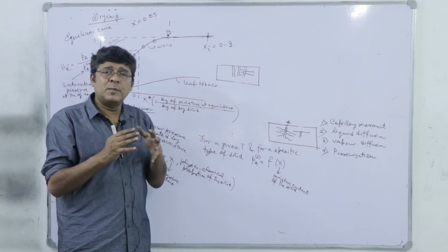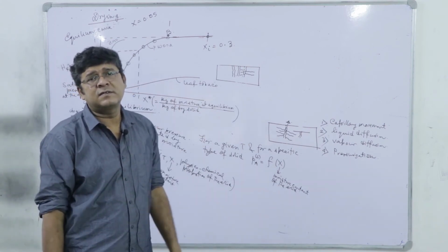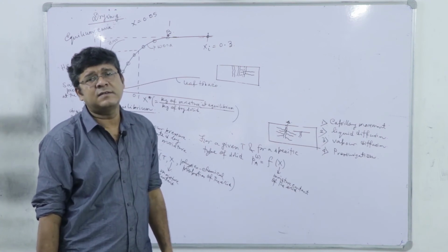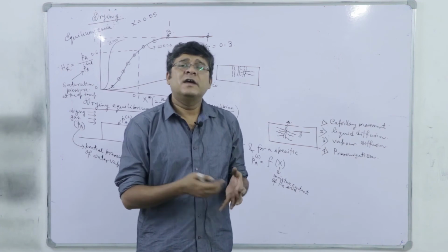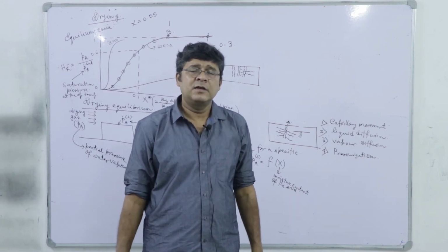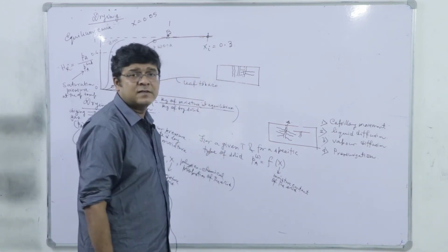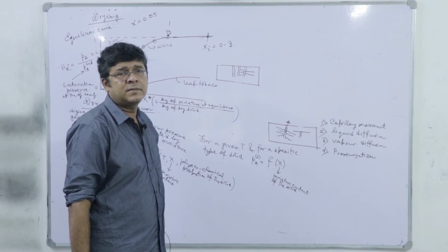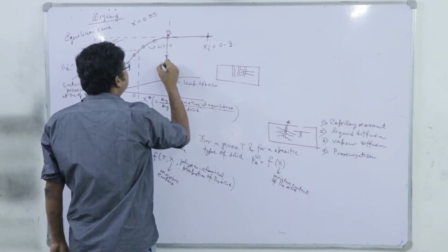So, that much amount of water which can fill the internal crevices, cracks, capillaries, etc., these are basically having intermolecular interactions with the wood fibers, right, and that is why this amount of moisture up to the point B is called bound moisture. Okay. So, this is referred to as bound moisture.